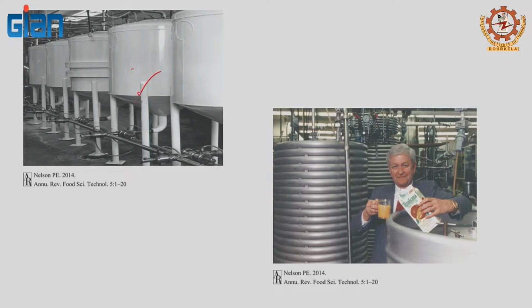So, for example, in Florida, where you have an aseptic packaging line, you can package them in small consumer type packages. This brings some flexibility for processing and then packaging at different time intervals. Now, this process is aseptic, so that means it is shelf stable. So, you do not need to worry about the product being spoiled as long as you maintain the sterility of this tank during processing.